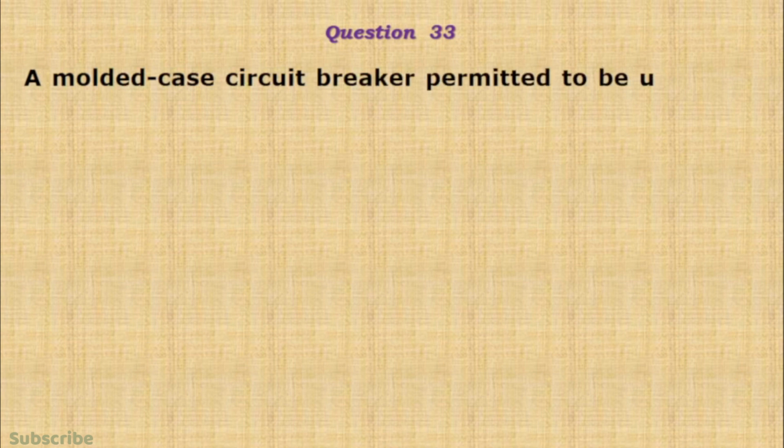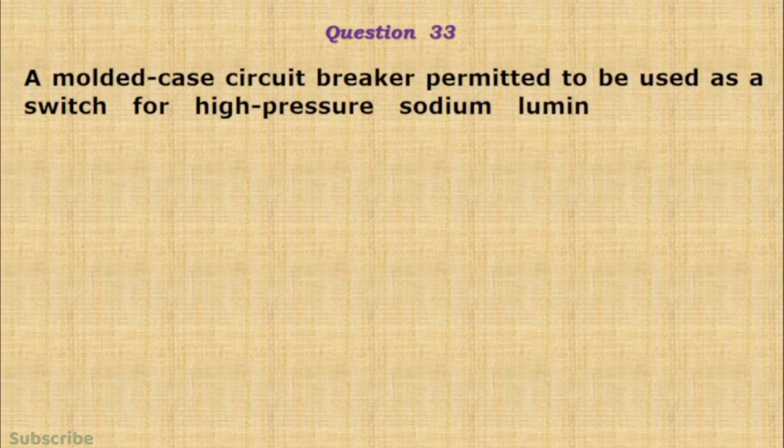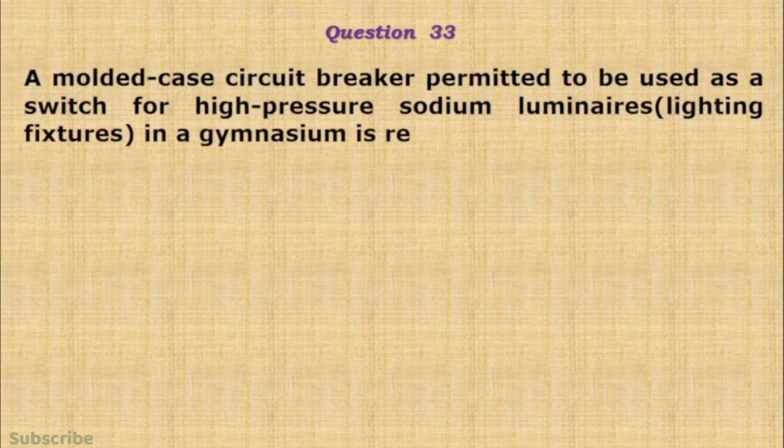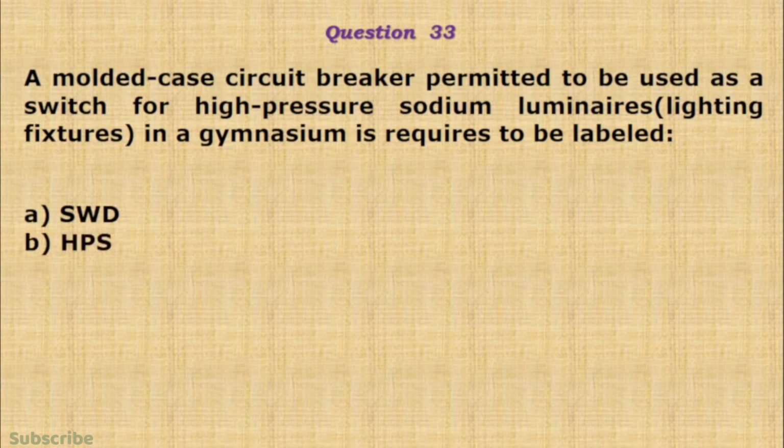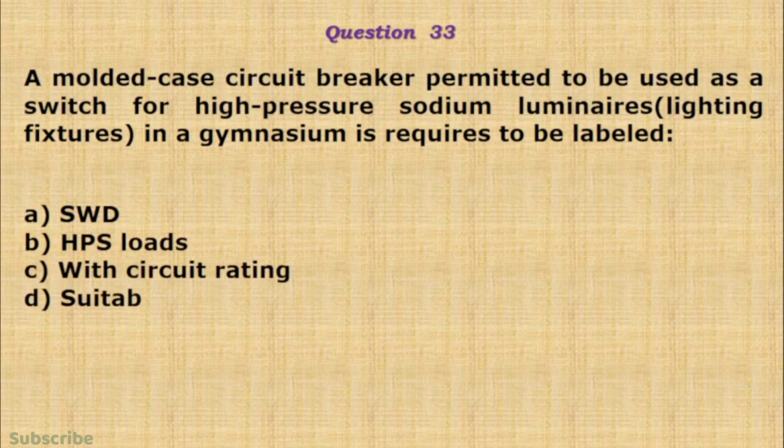Question number 33. A molded case circuit breaker permitted to be used as a switch for high-intensity discharge luminaires, lighting fixtures, in a gymnasium is required to be labeled A. SWD, B. HPS loads, C. With circuit rating, D. Suitable as switch for luminaires, lighting fixtures.